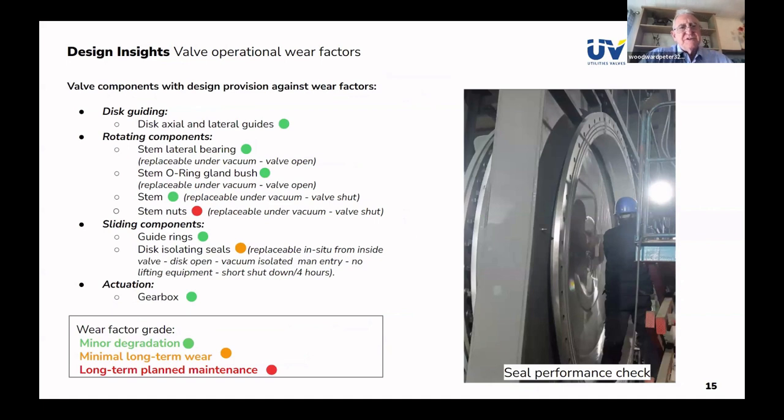The lateral guide is easy. The axial guide, we have developed a means of controlling the compression on the downstream face, irrespective of the fact that the wedge still wants to move. We have what we call a seal guard, which is an outer ring of PTFE, which acts as a guide, and it also acts as a guard because it's outside the main seal area circumferentially, and it prevents ingress as well into that area.